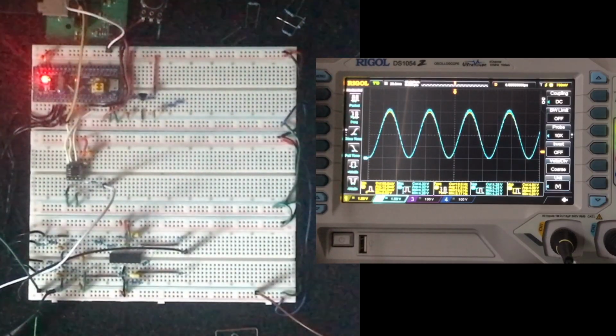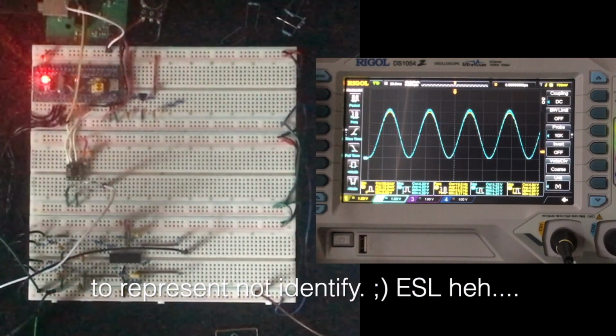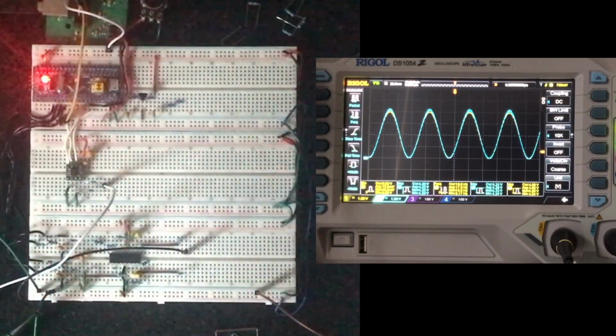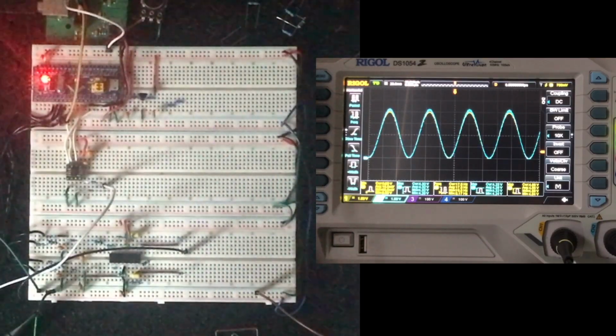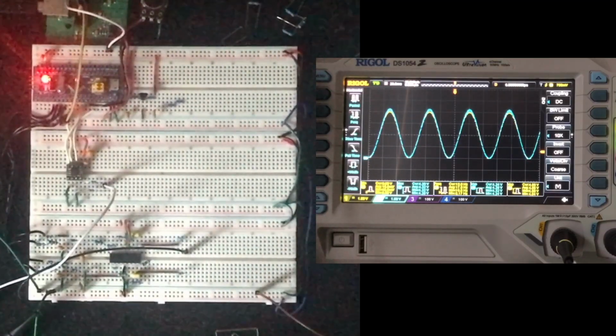Now you only have about 4 values. That's 4 samples, or a little bit over 4 samples, that you can have to identify that same wave, right? So if you can only define it with 4 samples, you're not going to get very much fidelity out of that. And because of that, when you combine that with only a 12-bit resolution, it's going to hurt a lot, right?